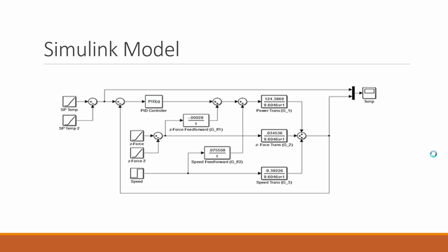And so we built the Simulink model in order to see how well our KP values model our tool temperature. So we have 3 variables instead of 1, and we treated 2 of them as disturbances with feedforward controllers. So I took the KP values and the tau value, which we only have 1, into the transfer function, which is KP over tau s plus 1.